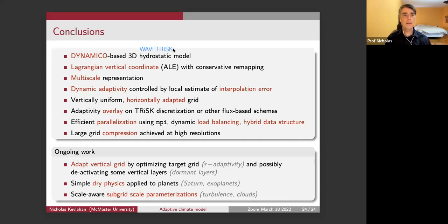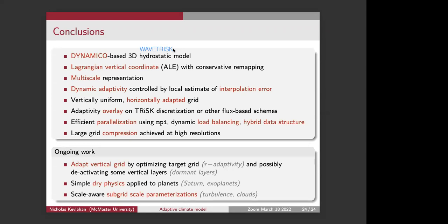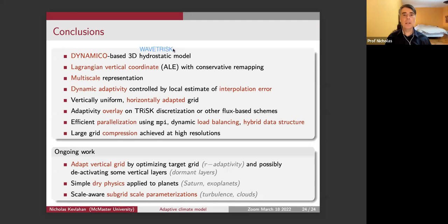Okay. Are there any other questions? Maybe for FEM spaces, you have linear or even higher order? We're not using finite elements. It's a second order method. So it's a finite volume, finite difference method, and it's second order in space.